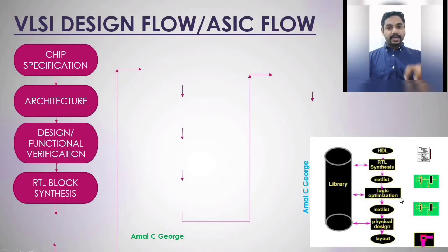So, when timing constraints are met with the logic synthesis, the design proceeds to the next step called design for testability, DFT techniques. So, logic synthesis is the process of translating and mapping the RTL code written in HDL, HDL meaning Verilog or VHDL, into technology gate level representation.